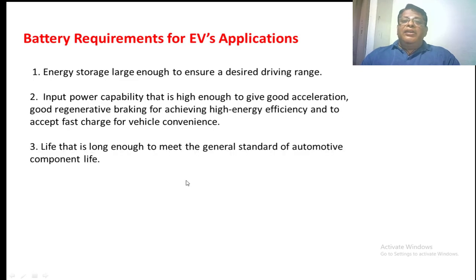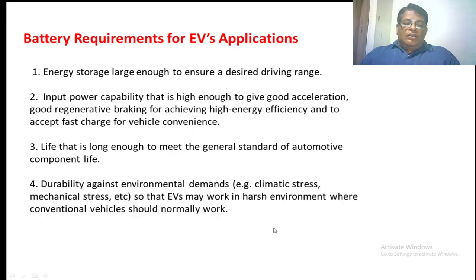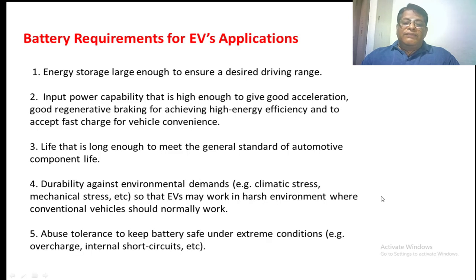The life of the battery should be almost equal to that of IC engine based vehicles. It needs durability against environmental demands so that an EV can work in a harsh environment where a conventional vehicle would normally work. There should be good tolerance for the battery to stay safe under extreme conditions, namely overcharging and internal short circuit. These are the requirements of a battery when you are going to use batteries in an electric vehicle.